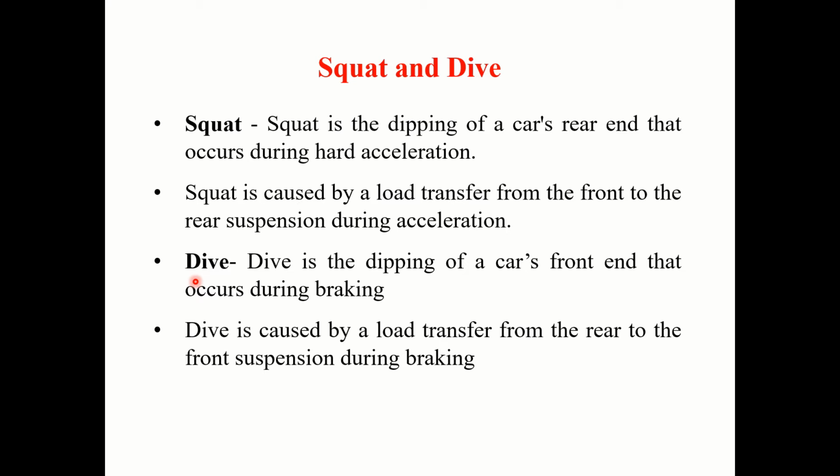So dive is something like an opposite phenomenon. It is the dipping of the car's front end during braking. So again, dive is caused by load transfer from the rear to the front suspension during braking. So now the question is, because of squat and dive, it leads to pitching of the vehicle. How exactly does the suspension need to be designed to reduce the squat and dive phenomenon?